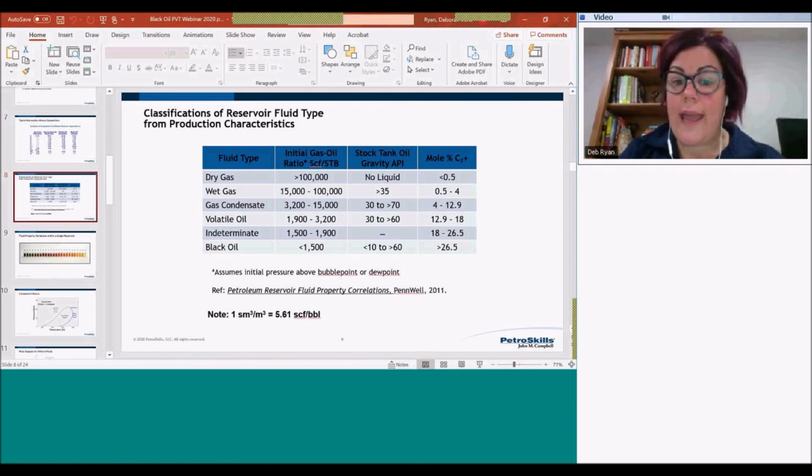Yep. So something at 18,000 we would put into more of a wet gas classification, where we should be seeing that the reservoir fluid is still going to be coming up as 100% gas, and that we're not seeing that fluid separation until we hit the separator at surface. But you can see as well, these are only indications. So 18,000 might still be a gas condensate, but really one of the things you're going to want to understand then is your C7 plus components with that.